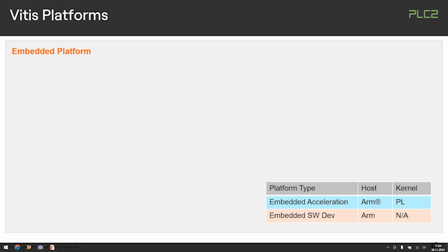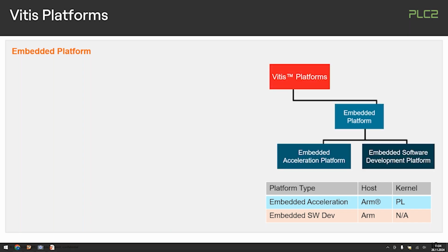basically. So what does it mean in the end to build something like that? You are starting off with the classical idea of what do you need from your IO level, what do you need from your fabric, what should be done in the logic, what should be done in the PS part. So the sequencing, or the partitioning, of the design is very mandatory and important with these approaches.